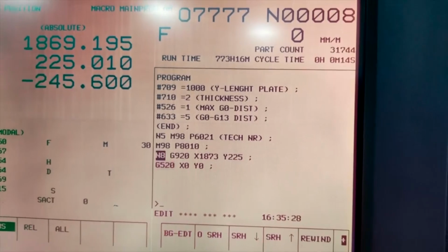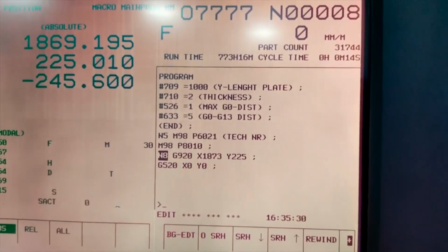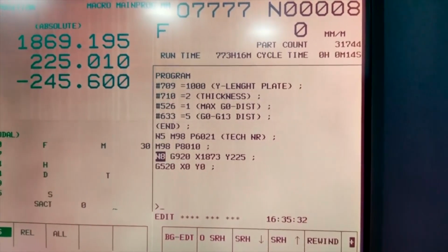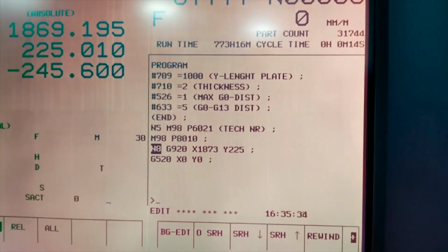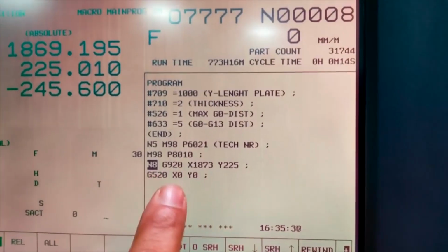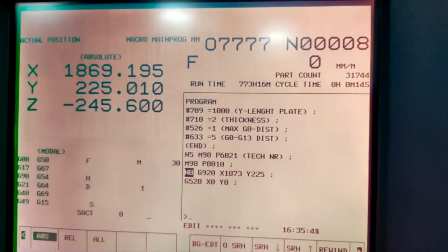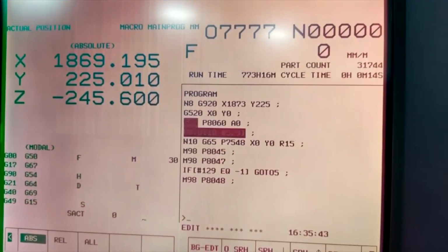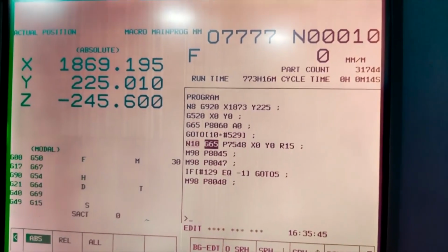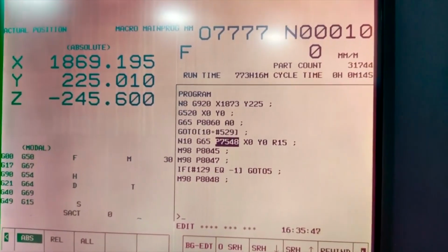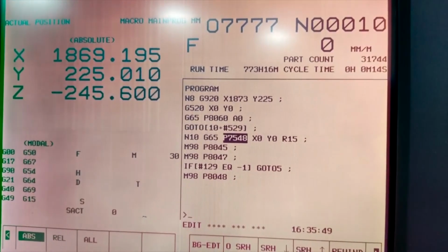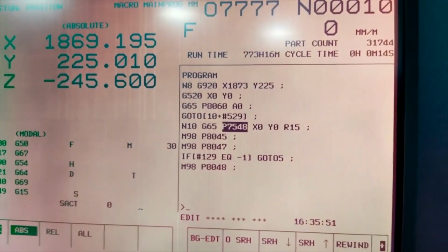So there should not be any gross or you can say significant deviation. Minor deviations are okay. We have to set the program 0. So here there is no other requirement to set the program 0. So for demonstration purpose, we have taken just a sample point on the work part. Now we are carrying out the actual machining operation.